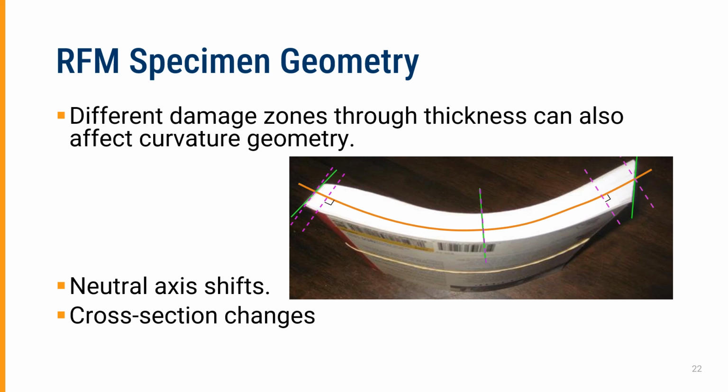The other thing is the geometry of the specimen, and this is why Timoshenko came up with the method that I showed on the previous slide. The theory is that all of the surfaces retain their relative position. So the ends retain these nice perpendicular to the neutral axis orientations.